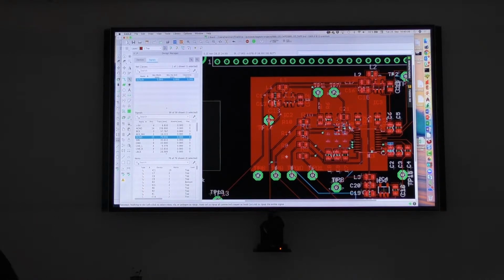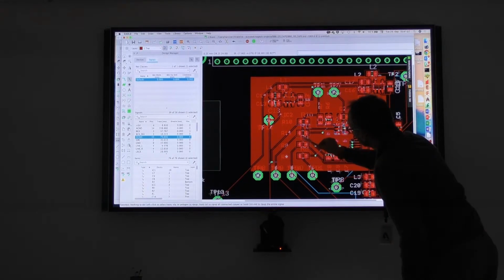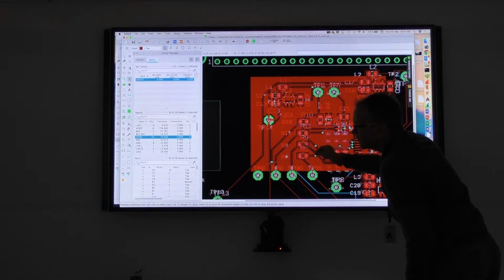So that's also a problem of the design you're doing. And here again, the designer has to decide what's good or what's bad. That needs electronic skills and understanding what we are doing here. So, for example, one of these orphans, maybe this one or this one, that have got a track underneath them. You might want that orphan connected to the ground to provide some shielding.